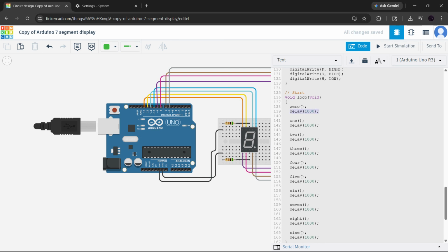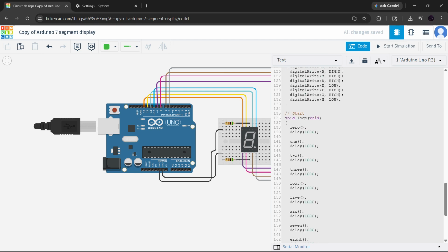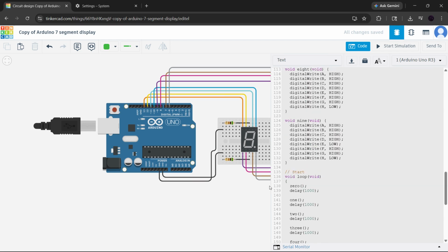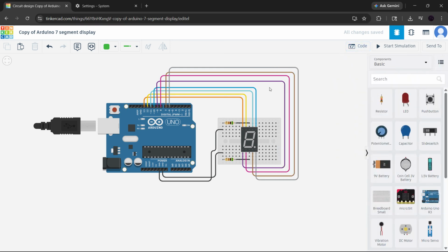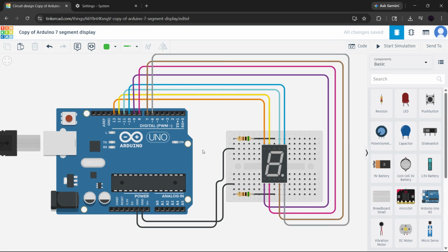You should also check for infinite while loops. If your code keeps repeating inside a loop without ever breaking out, Tinkercad may stop the process because it's running too many cycles without updating the interface. So review your logic carefully, make sure every loop has a valid exit condition, and if needed, simplify your code to test one part at a time.